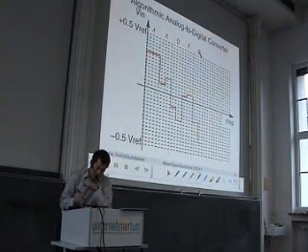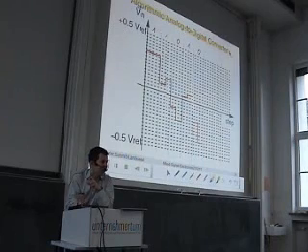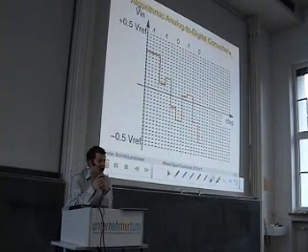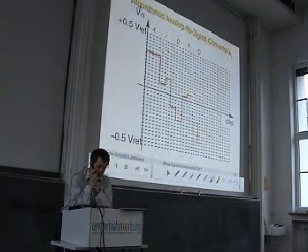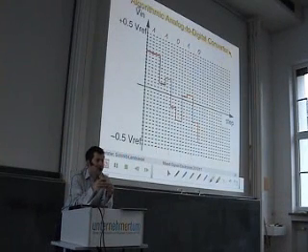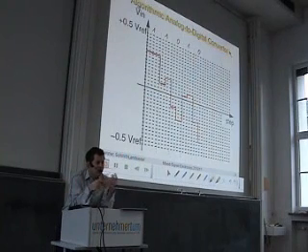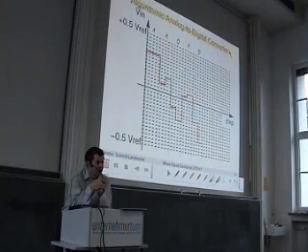This is what people call an algorithmic analog to digital converter. Well, it's simply a modified version of the successive approximation converter. It is a variant of this. The idea is the same: to have a binary search technique to figure out the value of the input voltage by doing this question and answer game and doing this binary search.